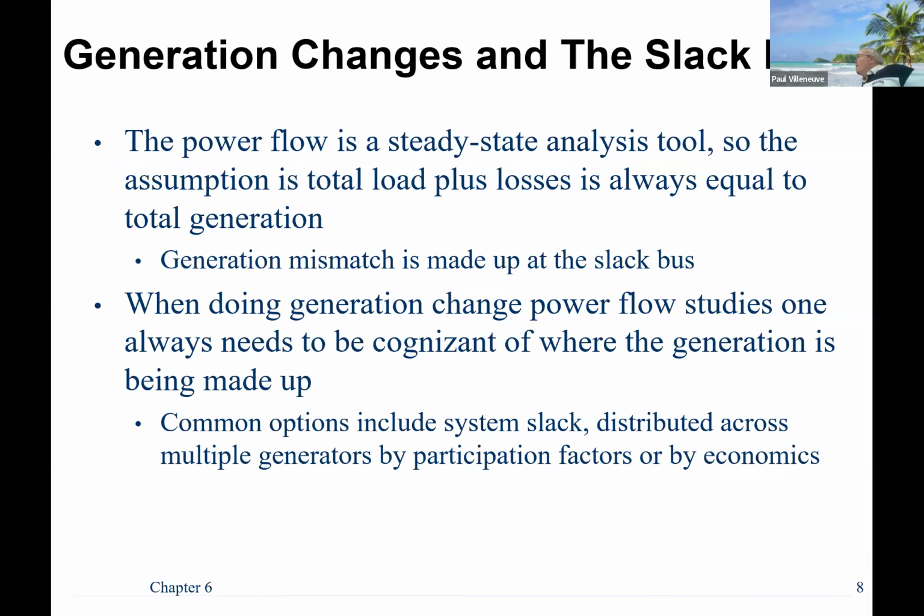So remember, we want to make sure that load flow is a steady state analysis tool. It doesn't look at faults and it doesn't look at transients. So it's only good for looking at whether the system is operating stably, not considering those other issues. But just because it's a steady state parameter, that doesn't mean you had better make sure that your system has all the criteria being met.